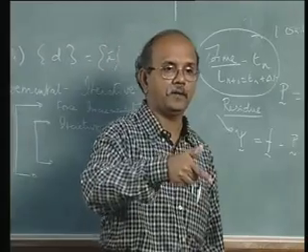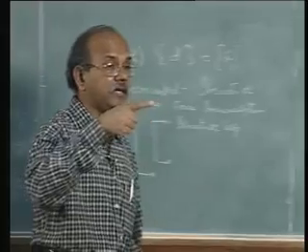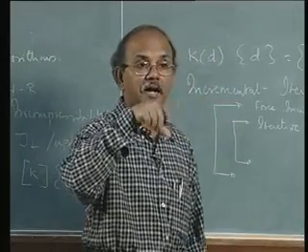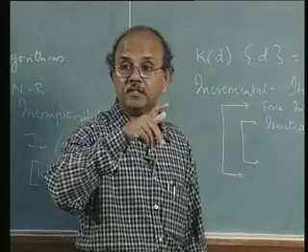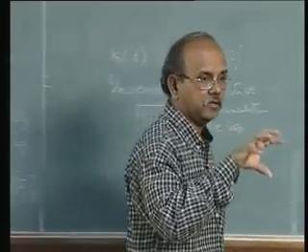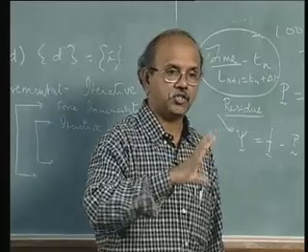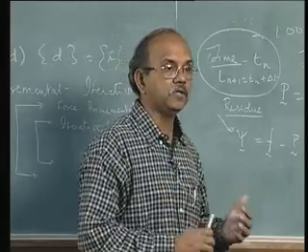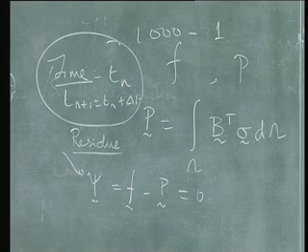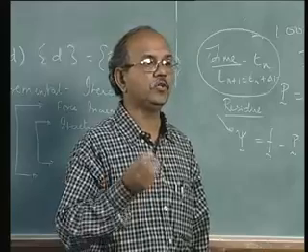In the same fashion, they will do the other thing also. Suppose you put 0.1, and in the iterative process, I said already that I have to get convergence. What is convergence? That means your internal loads developed by your stresses, which is P, and external loads match. That means the error residue is very small. If this residue is not small even after very many iterations, usually you put a limit.